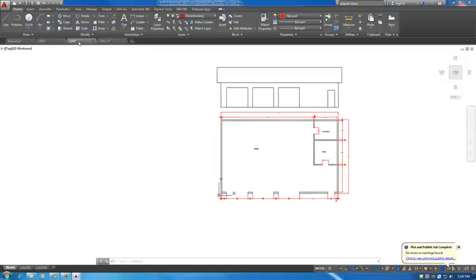Another thing we need to talk about is roofs. On a house, a standard roof structure is based off a 12-inch system. You'll hear a 4/12, 5/12, or 6/12 pitch on a roof. Those are standard terms when talking about roofs. A 4/12 pitch means you have 4 inches of rise for every 12 inches of run.